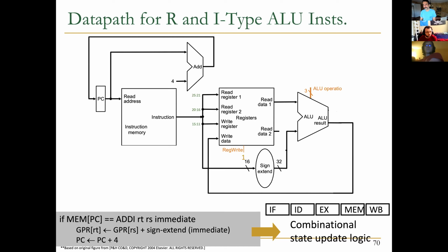How do we wire this to the ALU? You could just use a flip-flop. Right, so you use the mux here. It's simple, right? So use a mux, and then here you need to send the right signal to the mux, right? So is I type. If I type, then you select this input. If this is 0, meaning that this is not I type, on the other hand, this is R type, so this input would be selected and wired to the ALU, right? So whenever you need a choice, a MUX is the right architecture element, the right logic gates to use, right? The same here.